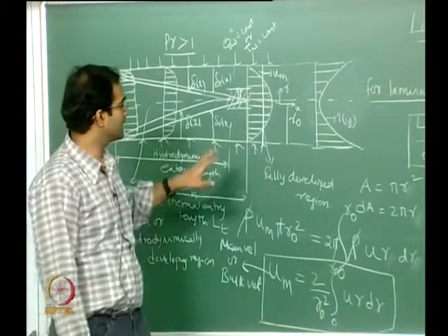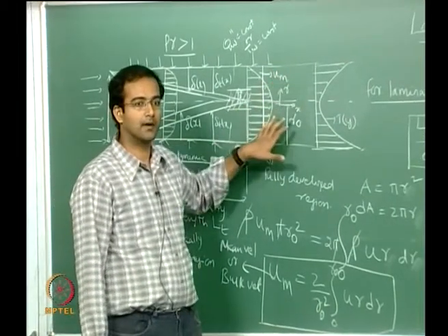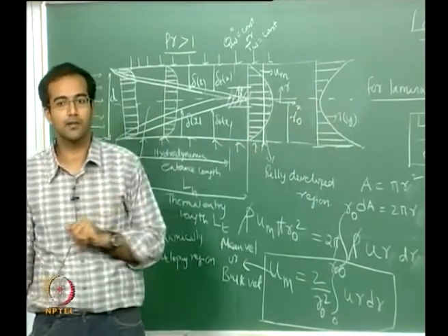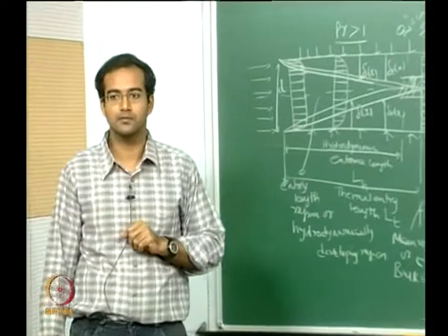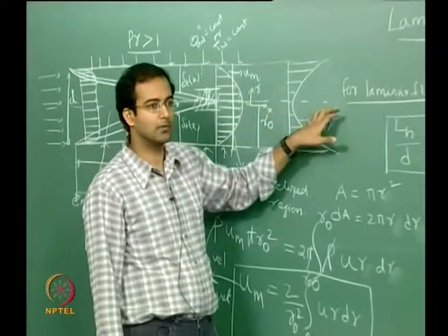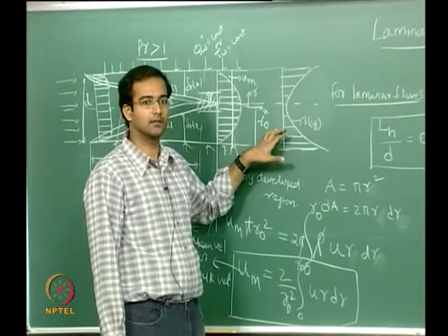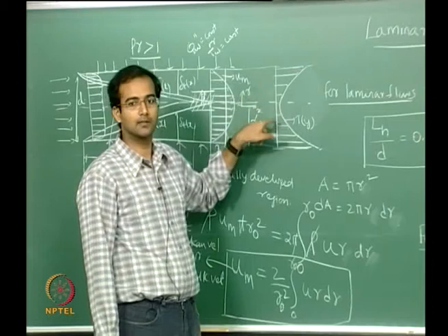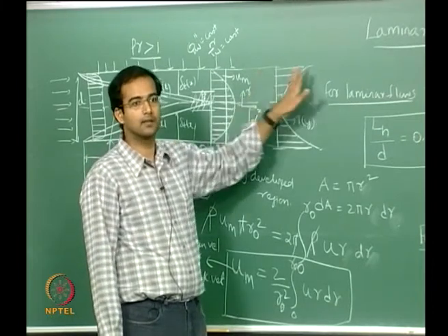So therefore, unlike the velocity profile, which shows a constant behavior, the temperature will never be a constant value, correct? So you will find the temperature of the fluid anywhere that you plot will keep on changing with respect to x at any y location, or even at the wall, that also keeps changing.